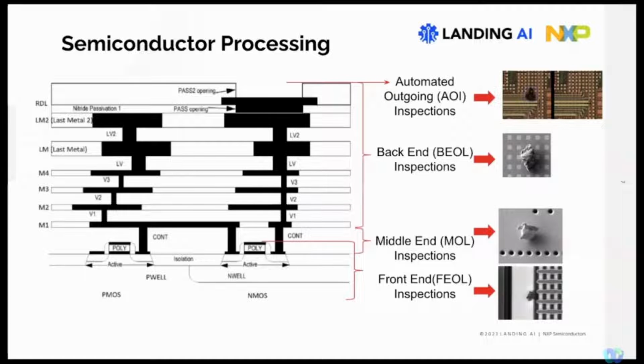As you can see, there may be two types of transistors, PMOS and NMOS, which are just different types of transistors. And from the active region to poly and contact, as you go up the line, you build up metal lines, interconnect lines, to access those devices in the chip to make the functionality of the die or the chip that we process.